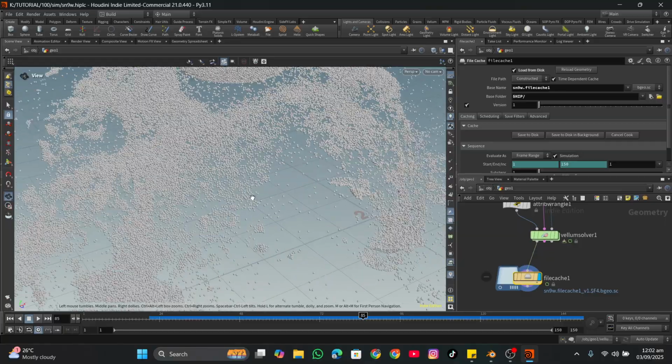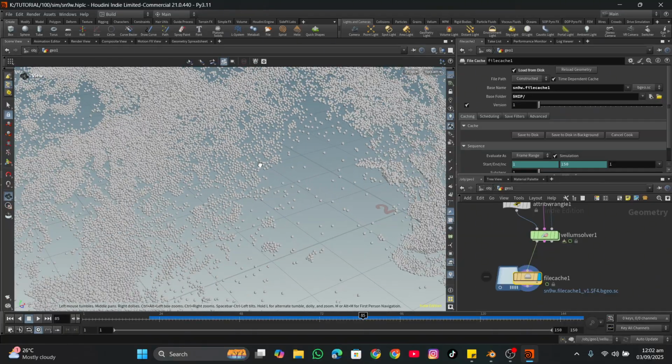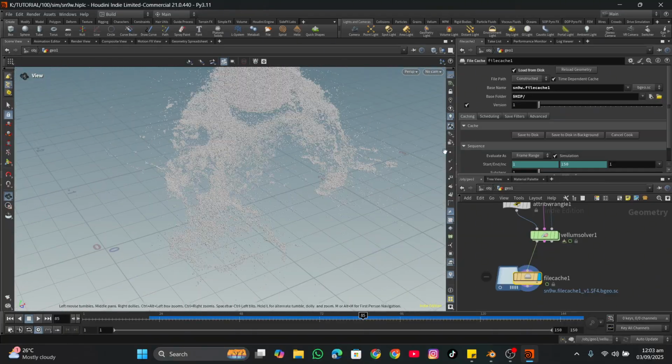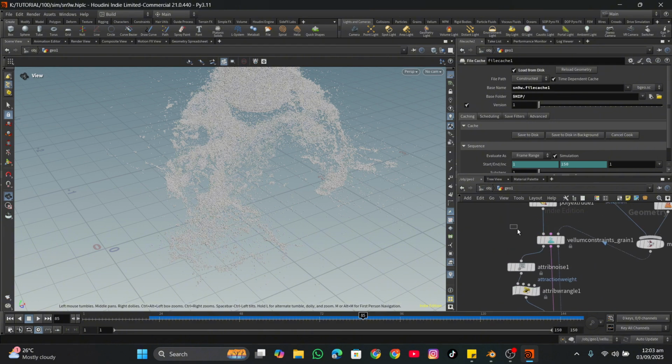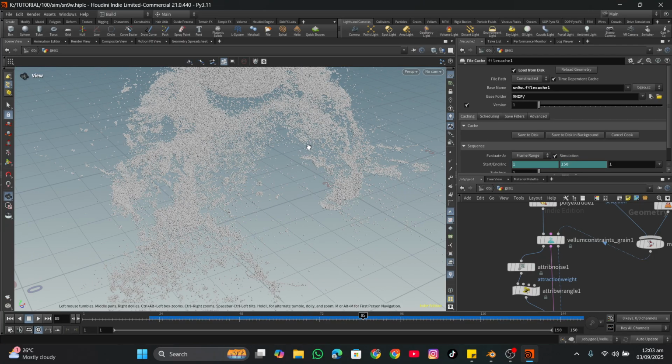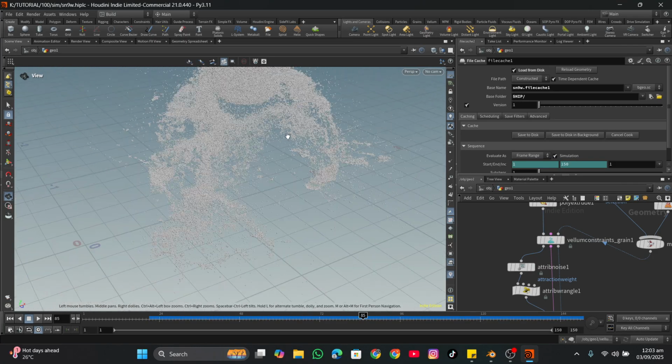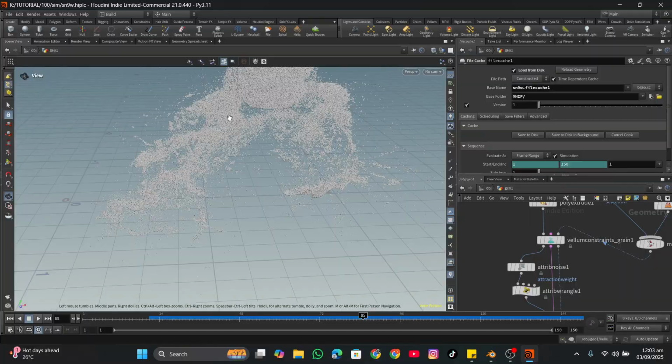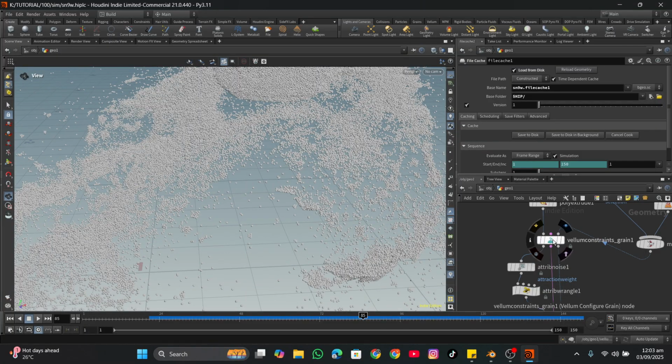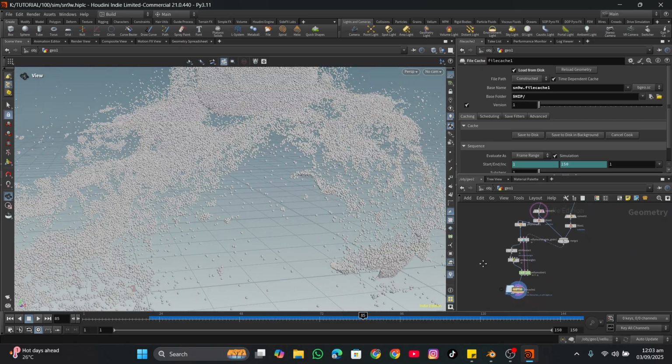One thing you can try to avoid some of the spherical condition is, first of all, you can increase this number to a higher value, and you will not even be able to see those smaller bits, right? But if you still have this problem and your system does not allow you to increase the grain size, then you can do this one solution.